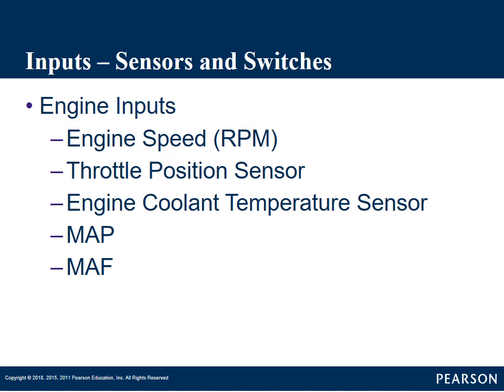If we have engine performance issues, if we have codes related to sensors on our engine, that can affect shifting in our transmission. There are many times when transmissions are condemned or attempted to be repaired when the problem was in the engine, not the transmission.